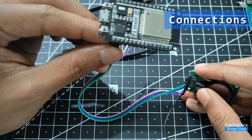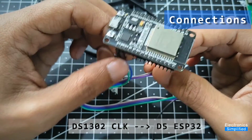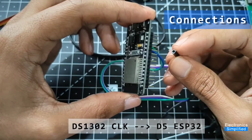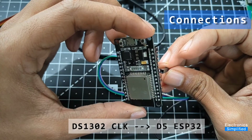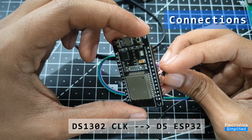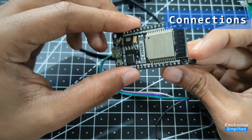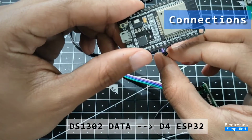and then the next pin is clock. The clock pin goes to pin number D5, so I'll connect it to D5. And then the next pin is the data pin, it goes to pin number D4.